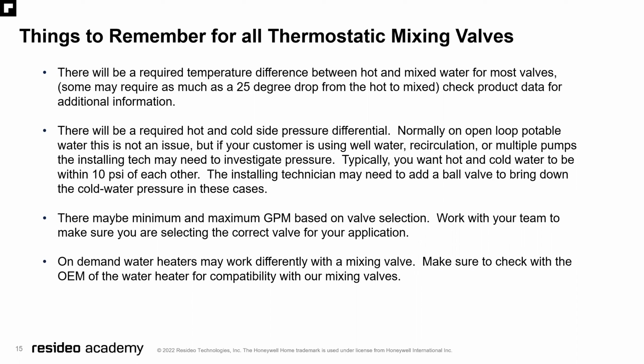Work with your team to make sure you're selecting the correct valve for your application. And last but not least, on-demand water heaters may work differently with a mixing valve. Make sure to check with the OEM of the water heater for compatibility with our mixing valves.